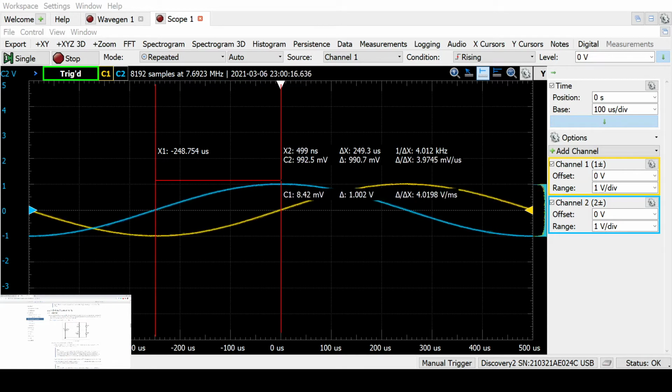So use the circuit below to measure both the voltage across and the current through the 1k resistor on the scope to see the phasor relationship between the two. Also use the scope to calculate the instantaneous power through the resistor. So we are using a small resistor here which will help us determine the current flowing through the circuit, which is our sense.